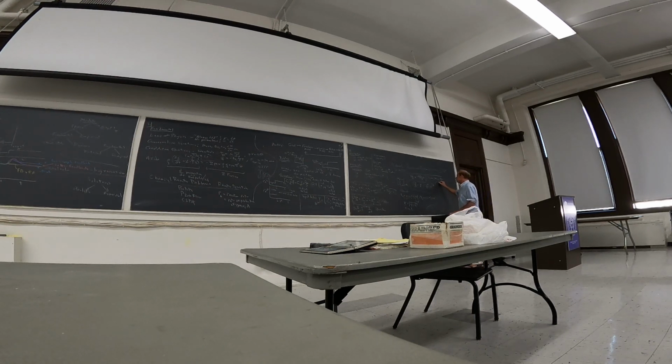So I can rewrite the left-hand side as d/dt of e to the t over tau times CA, which is equal to e to the t over tau times CA in over tau. How do I know that? Well, if I take d/dt of this, I get the exponential times dCA/dt, plus CA times the derivative of the exponential, which is 1 over tau times the exponential. And that's equal to the right side. This is a total derivative, so I can now integrate it.